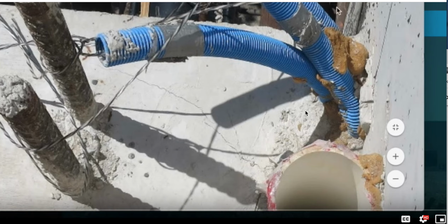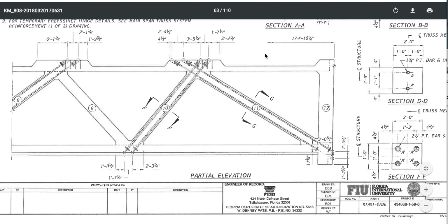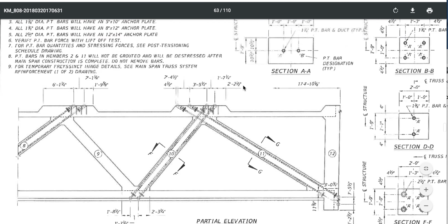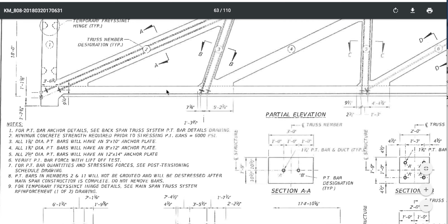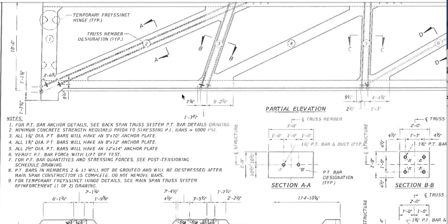When he took off the clamp force at the back of number 12, it killed the tied arch system back to here. And it's as simple as that: this system was acting like a tied arch system. They missed it with the deflection and not tying in every single crack. And this is why I say I'm a crack freak, right? And why cracks matter. They are signaling everything. Those little bits of cracks are telling you what your structure is doing.